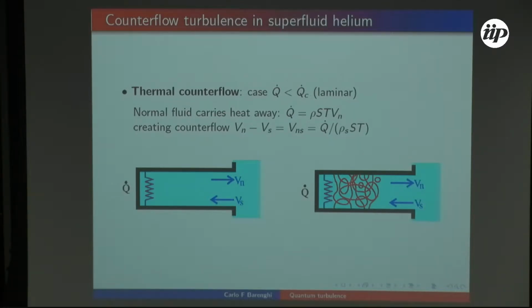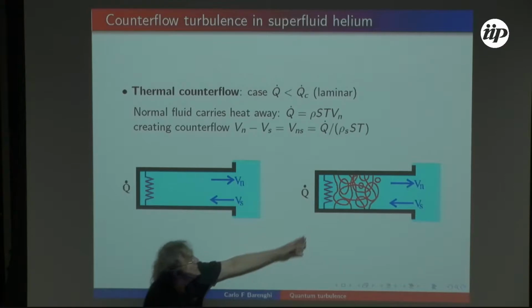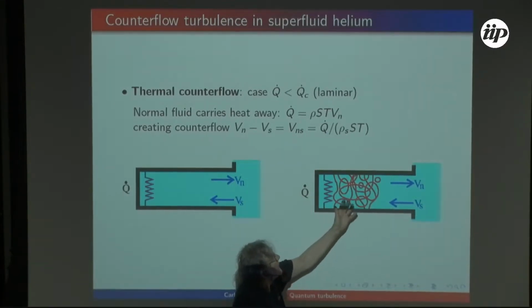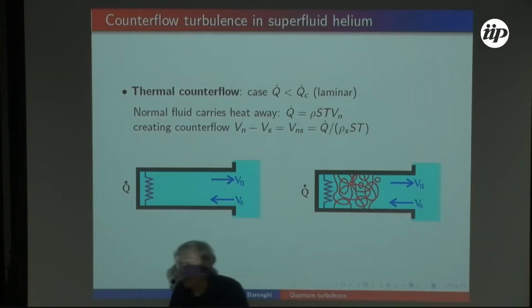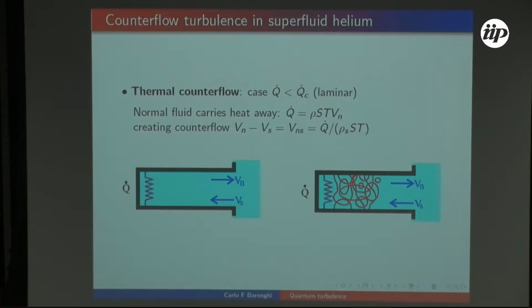So it is important. Typically what you see is that if the heat flux which you apply is small enough, you have this perfect heat conduction, which breaks down, however, if you try to push the counterflow to very large values. When this counterflow is very large, the ideal heat conduction breaks down, and you have lots of vortices. And vortices are always energy losses, because this motion around the vortex lines means that you're supplying energy for going nowhere. You're just erratically moving.